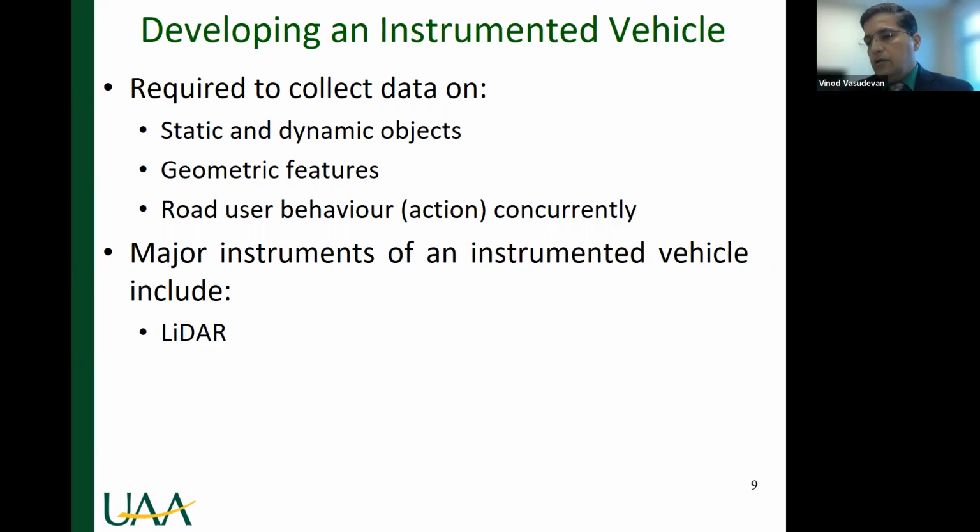One, you need a LiDAR, because LiDAR has a lot of capability, especially measuring distance. The video camera, on the other hand: LiDAR's advantage is that it can measure distances, but to detect an object, a video camera may be a better option. So if you have a LiDAR and a video camera, you can use them together to get a better idea of the objects around.